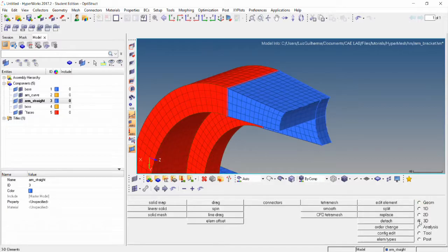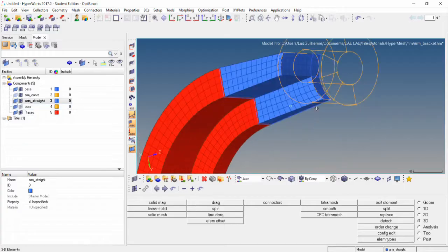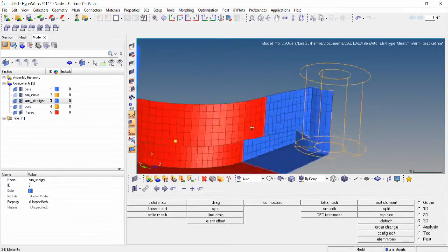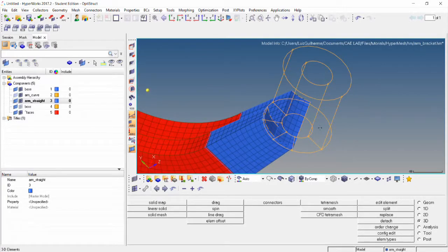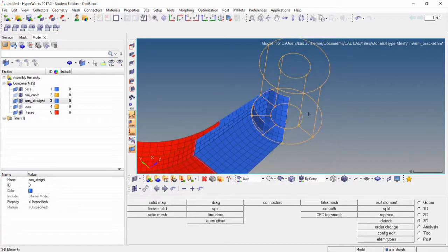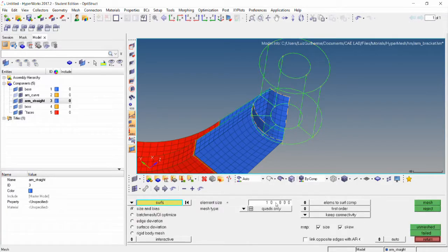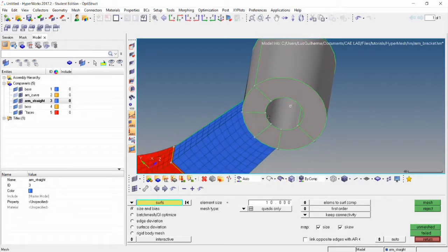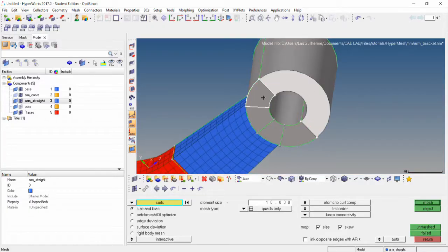We're going to move on now to the last component, which is the boss. This is what it looks like. So I'll call this surface the bottom and this the top one. We're going to start by meshing the bottom surface. So go to the 2D page, Auto Mesh panel. I'm going to turn this to the solid visualization mode. It will be easier to select these surfaces.